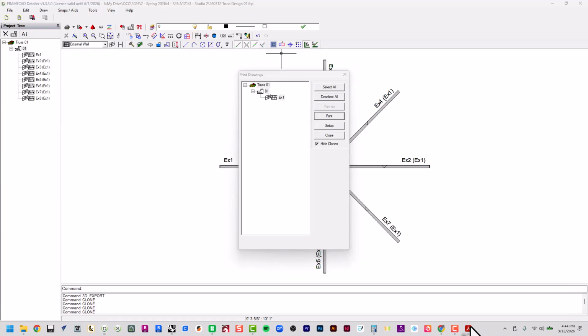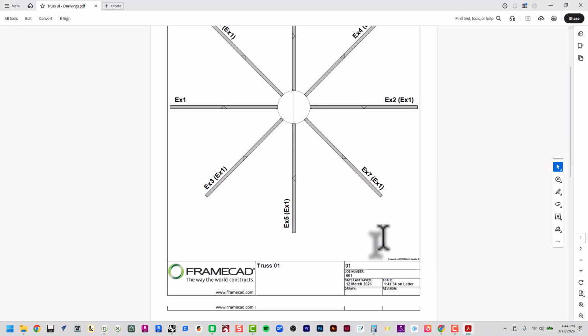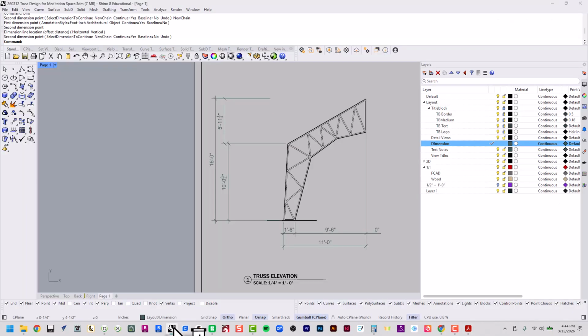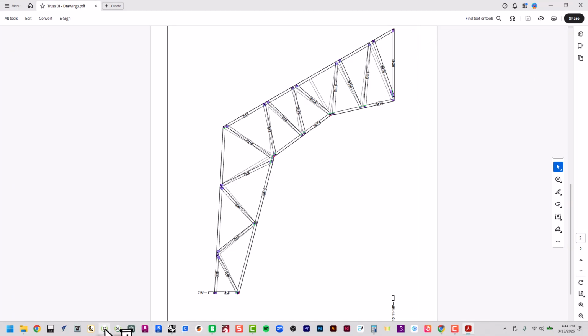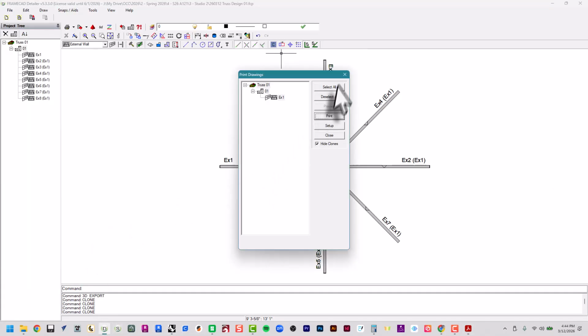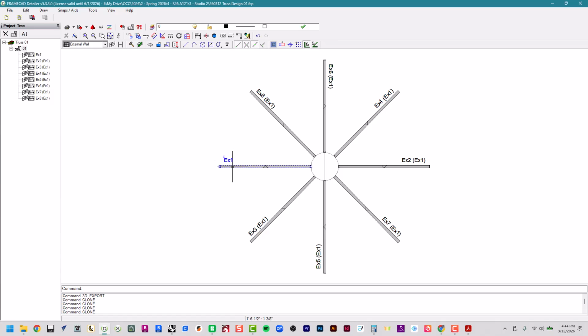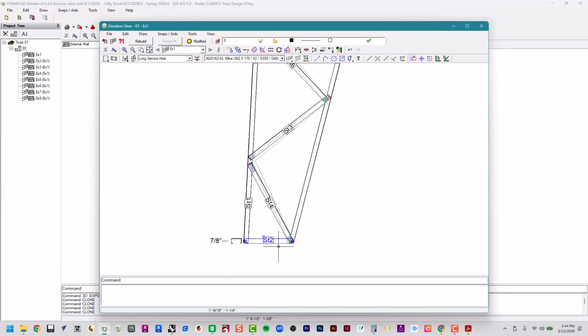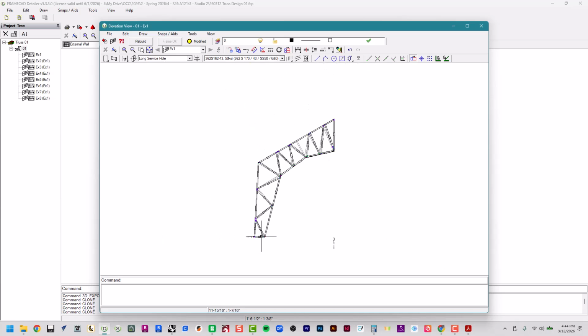Now, if I wanted to, I can go into the elevation view. Since I've changed the design so much now that I have the Detailer, I could go into this elevation, EX1, double click it, and just get rid of all the lines. I don't really need the lines anymore. So I'll select all of this, and hold shift as I deselect all of the actual studs.